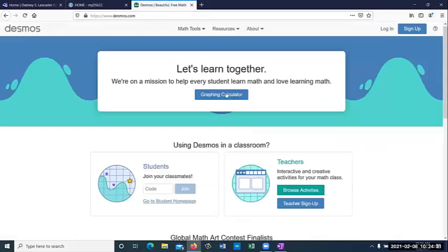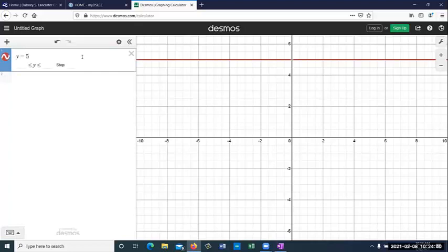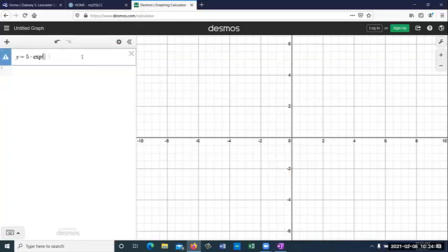But because it's of an exponential nature, things happen pretty quickly. So again, if I do y equals 5 times e to the minus t, you can see that after 6, 8, 10 seconds, the voltage has almost gone to 0. It's only in that first number of time constants. If you take 1 second, which was the time constant, here's after 1 second, 2 seconds, 3 seconds, 4 seconds, 5 seconds. So after 5 seconds, the value is getting very close to 0.